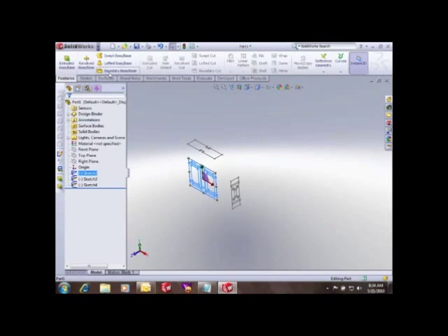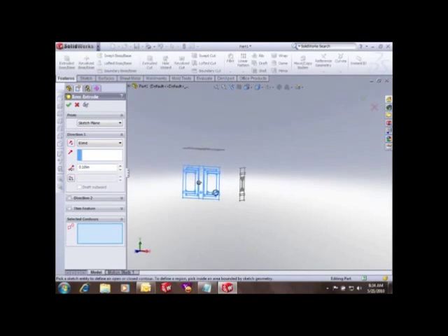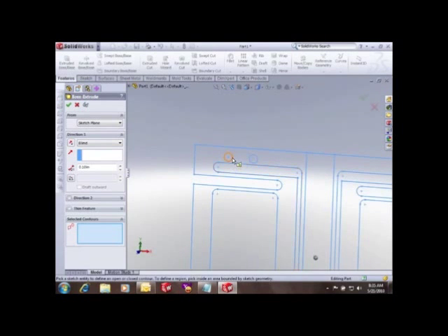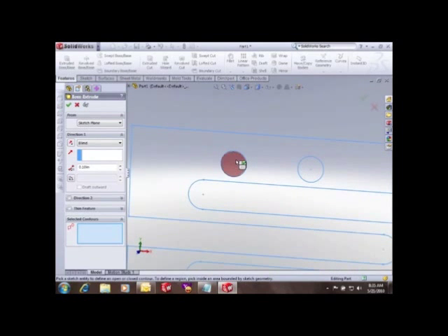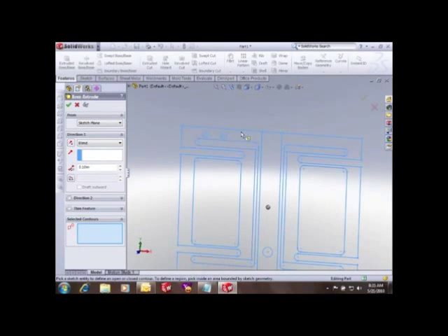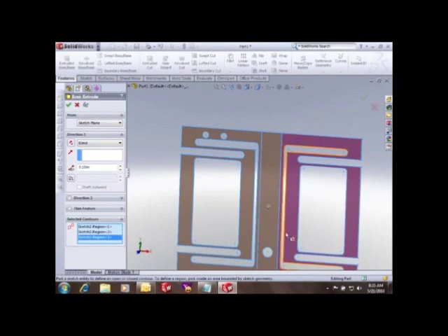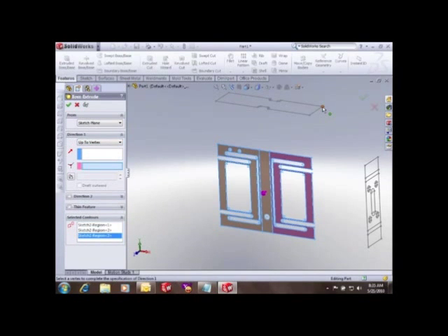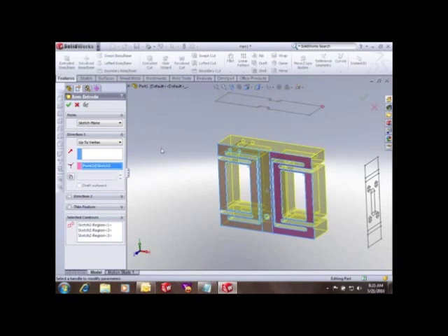And so let's go ahead and start by picking this sketch and extrude it. Now in an AutoCAD file there's usually a lot of different pieces of the 2D file that might make up the front view. I can pick from any of these different regions. You can see I can pick a contour or a region, which is basically expanding out from my cursor location and trying to find a closed boundary. So I'm going to pick a couple of different regions in this sketch to extrude. So I'll pick these three regions here, and then I'm going to change the end condition to up to vertex, and that allows me to use the point in the top sketch to be my extrude depth.